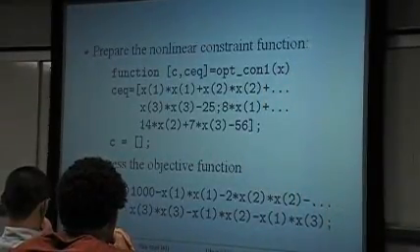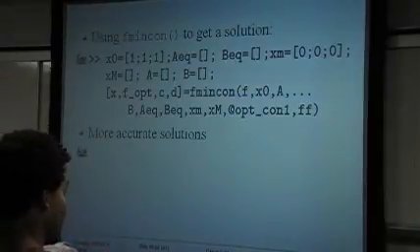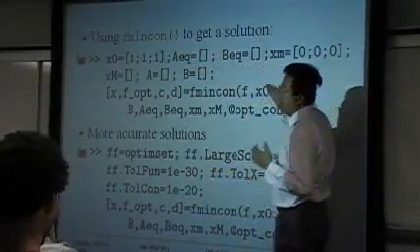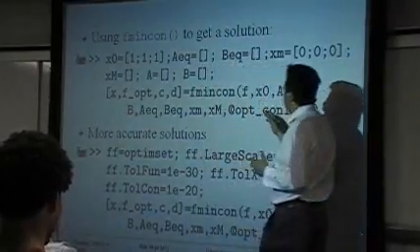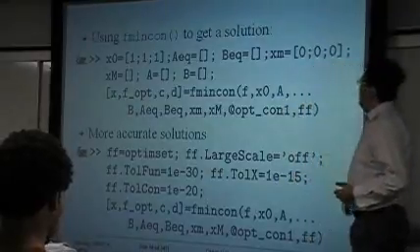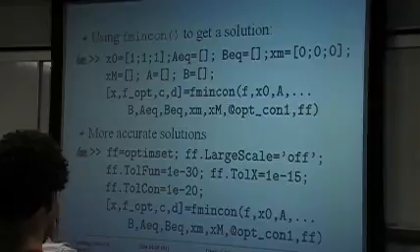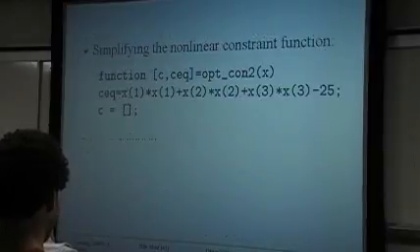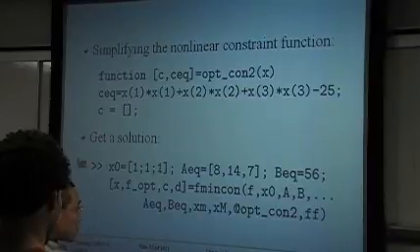And if we include all the constraints in this function, we do not have to specify A equal and B equal again. So we can assign now to x dimensions because we have already expressed this earlier in the function. So now we can solve the problem with the fmincon function and get the result. We should get the correct result, and using these two methods, the time required might be similar.